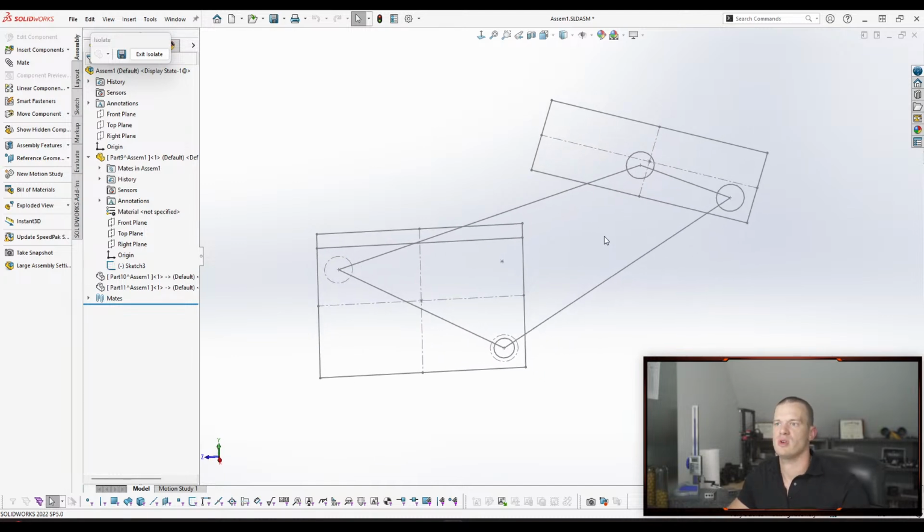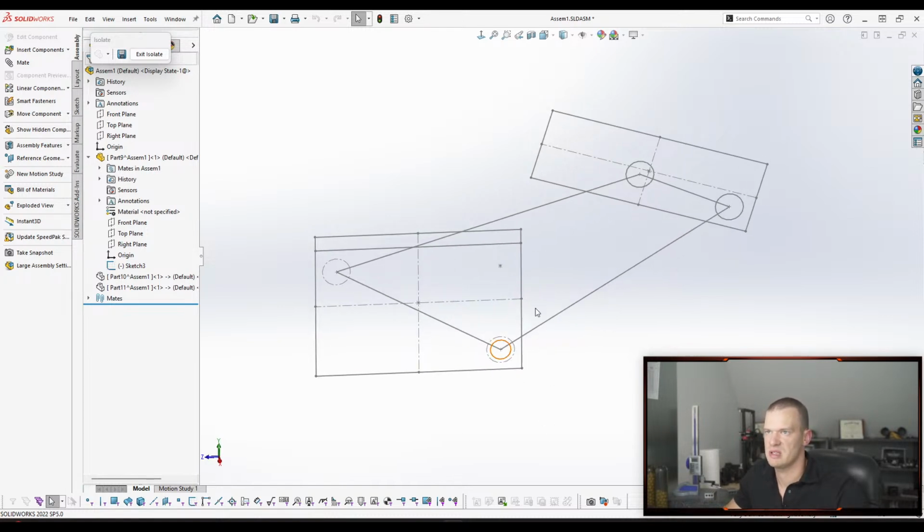So if you can keep your sketches simpler, that's better, right? You're spreading that sketch file over a bunch of different parts, so the more lightweight it is, the better. So if it's a relatively simple design like this, you might model in the 2 different diameters.